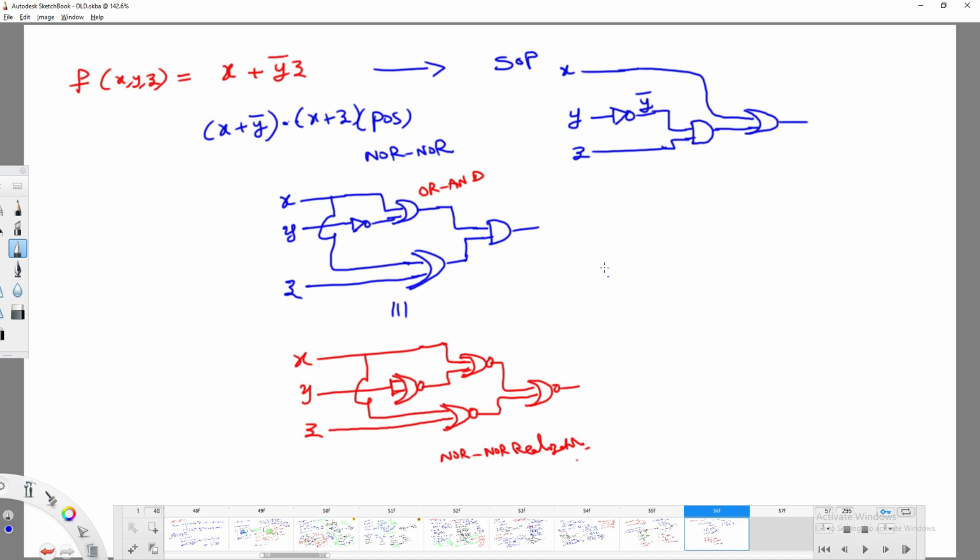So this is the corresponding expression, guys. But at this point of time, as it is in the form of sum of products, and as we represent it in the form of AND-OR gates, are we going to construct the respective NAND-NAND representation? Try to think. It couldn't be possible directly, because try to observe, if you bubble up here, you can bubble up here. Okay, right? Now, can we bubble up on the x side? No, it couldn't be possible.